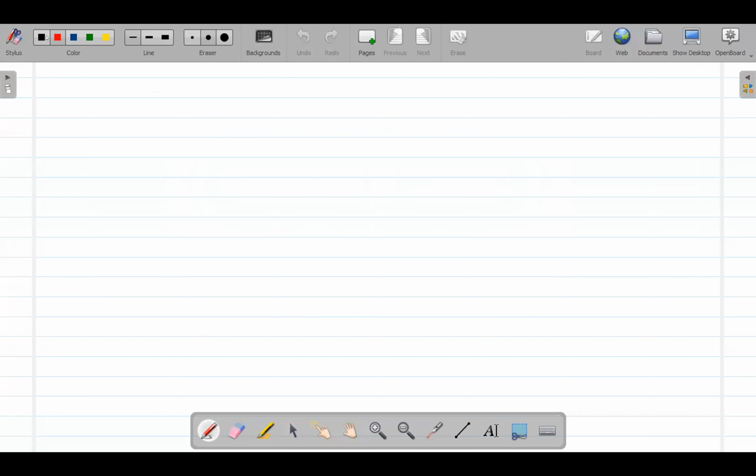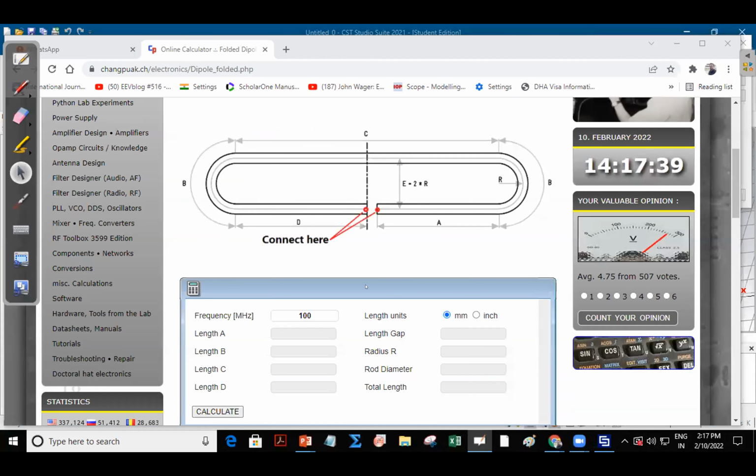This particular portion, if you are taking that curvature here, this curvature, last time we didn't consider it. We took it simply lofting by 0.2, because 0.2 is the radius of the wire. I mean to say, this radius we need to loft with the same angle, then only it will come as a good curvature. And similarly this one also. So what you have chosen is going to matter.